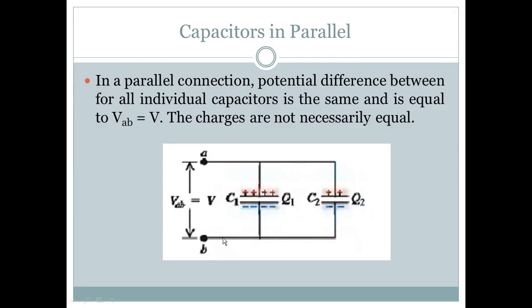So what does this mean? This means that whatever value that we assign for our input voltage, that input voltage would be the same voltage that would register across the first capacitor and the second capacitor, simply because each of the given capacitors has a direct connection to our voltage source.